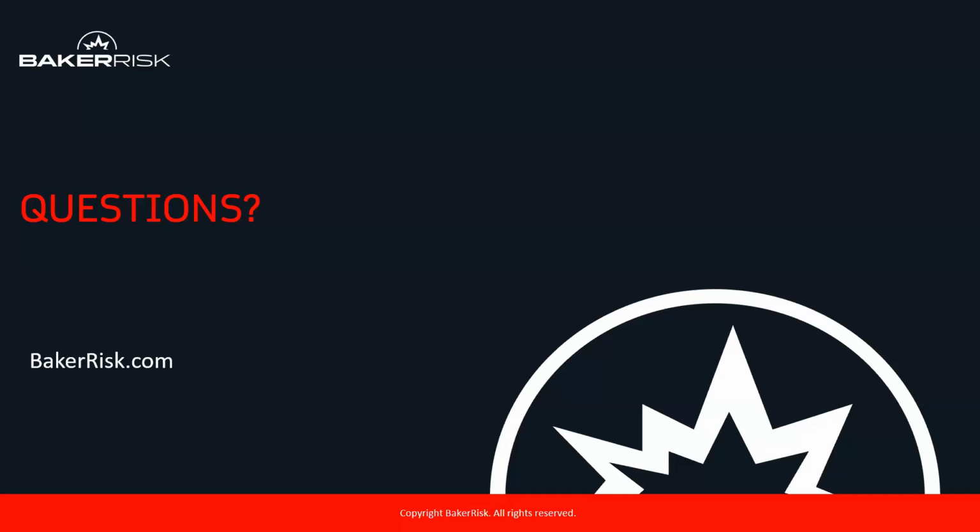Maybe a what-if checklist approach would really deliver all that you need based on the simplicity of the hazards. And if you have an existing process that's very complex and has lots of hazards, I would suggest using the HAZOP methodology, as it's very structured and helps the team make sure that all potential deviations are considered throughout the study.